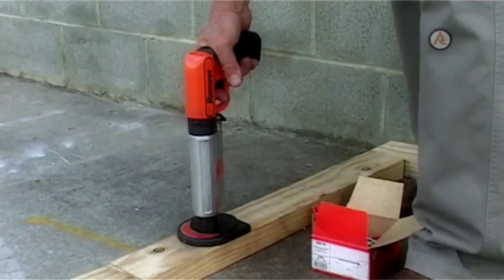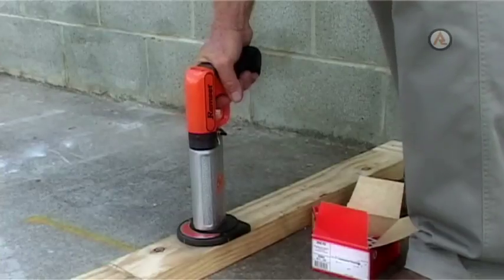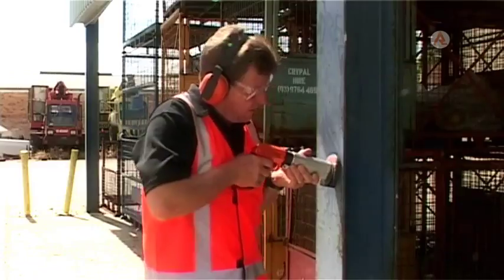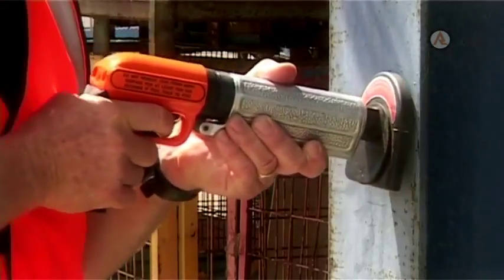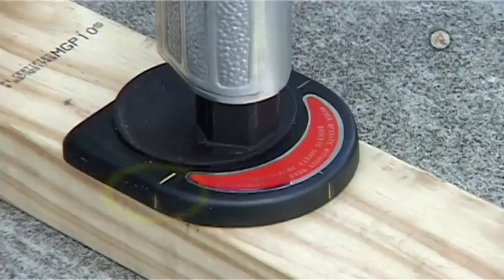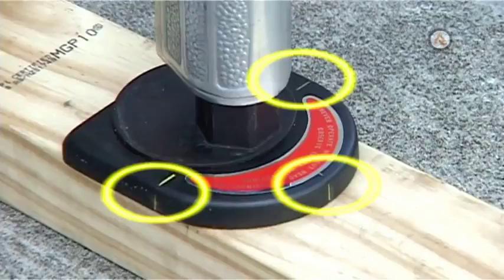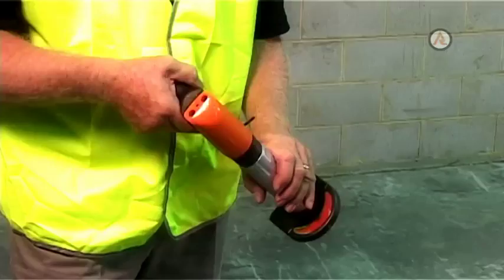All high-velocity tools are produced with a large guard to protect the operator from possible ricochet of the fastener, and precise angle fire control to prevent the tool from being fired at more than 7 degrees from being perpendicular to the work surface. Guide marks are located on the safety shield to allow the operator to properly align the fastener position. The tool is fired via a trigger.